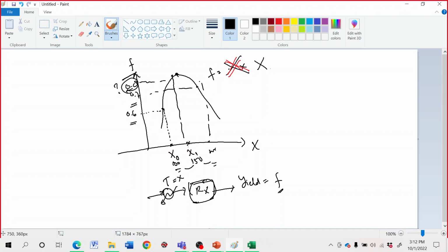So that means we will try to find it somewhere here. Make another one over here at 130 degrees C, and maybe another at 170 degrees C, and make some experiments to see if the objective function is increasing or decreasing. It's something that you can play around with. The point is that playing around with the set of independent variables, changing them, is what we call the function value method.